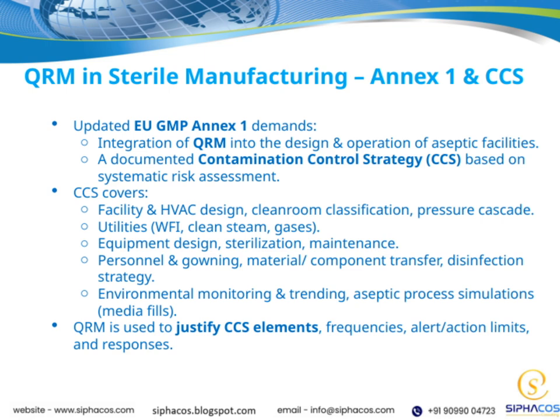Most importantly, QRM is used to justify each element of the CCS, determining the appropriate frequencies, establishing alert and action limits, and defining responses when issues arise. In summary, integrating QRM into sterile manufacturing, as emphasized in Annex 1 and the CCS, ensures a systematic, risk-based approach that enhances the safety and quality of sterile products throughout the facility's life cycle.